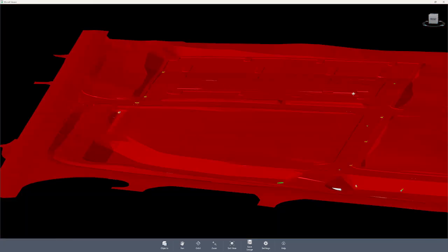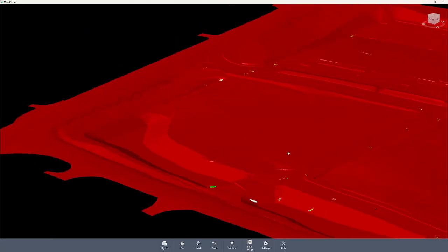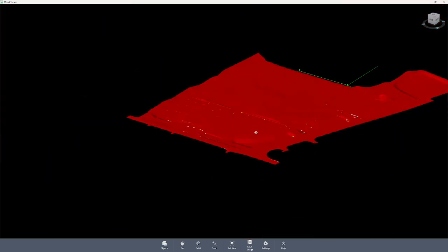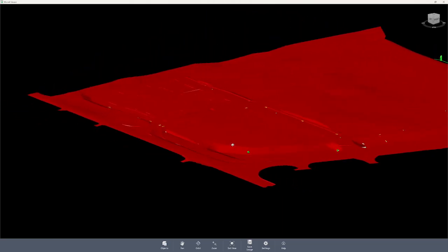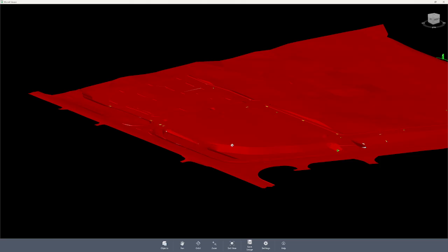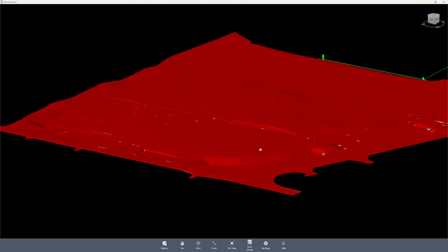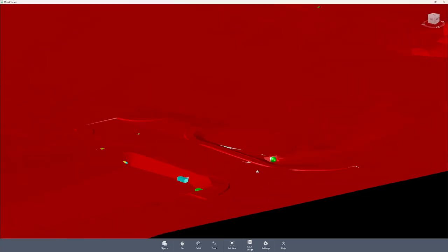If we had a 3D model of the building, we could include that in there. You can see all the basins. What makes this really useful, and what I used this for specifically here, was looking for any kind of stray lines or anything in my surface that you might not see in plan view, but when you look at it here, you could see, oh, there's a little spike right here, or something like that, that you could go and look at and say, oh, there's a spike there, we need to change that.